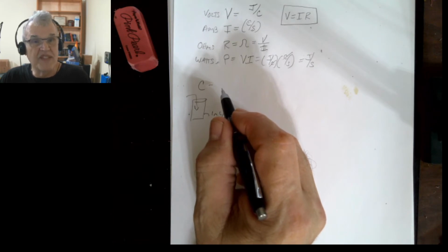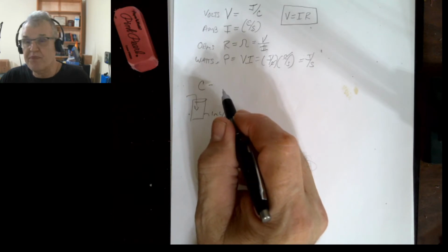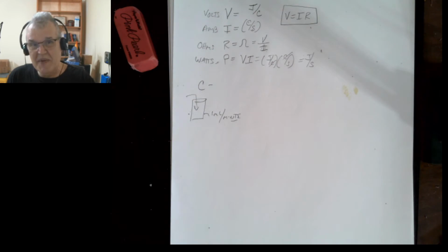And that would be a 1C rate. So if I do it at a 2C rate, that means I'm coming out at twice the current. I would be 5 amps coming out, and it would only be able to discharge that for a half an hour. I think I did mess it up. So if it's at a half C rate, then it's going to be 1.25 amps, and it's going to be able to do it for 2 hours.